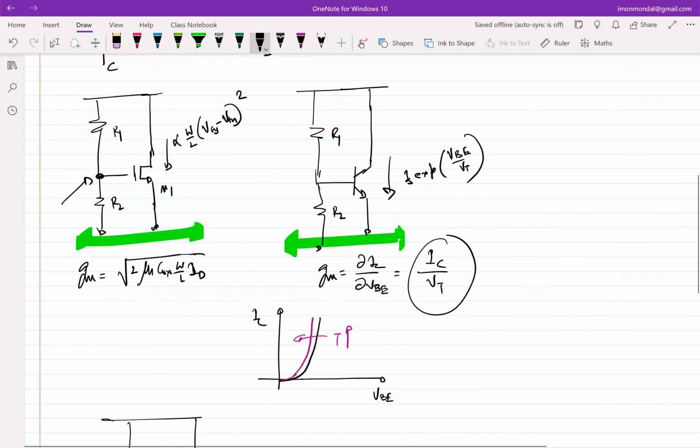Okay. So as it turns out, BJT has a property that it has a negative temperature coefficient. By that, what I mean is if temperature increases, the current increases. So that's how the device is. You see there is an electrothermal positive feedback here, because you turn on the device, there's some current flow. When you have some current flow, there's some power dissipation. When you have power dissipation, it heats up. When it heats up, current increases, and then you have more power dissipation. It heats up more and keeps on going, right? So it's a positive feedback.